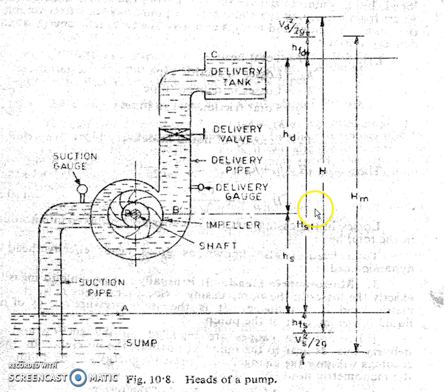In the total head, you do have some velocity head left with the fluid so that it will leave the delivery pipe. You will have some frictional losses in the suction pipe, some frictional losses in the delivery pipe, as well as some kinetic head, as we have already seen, left with the fluid leaving the delivery pipe.